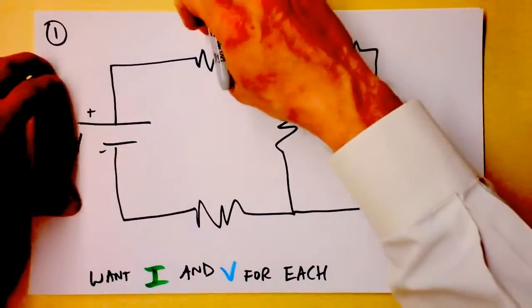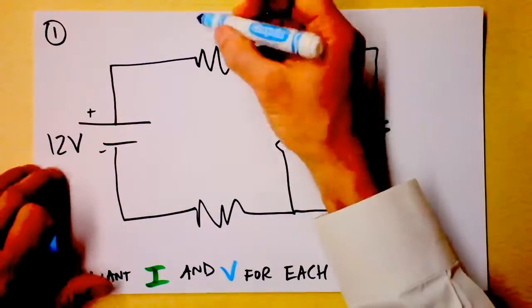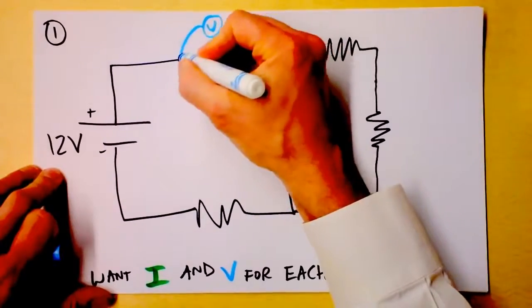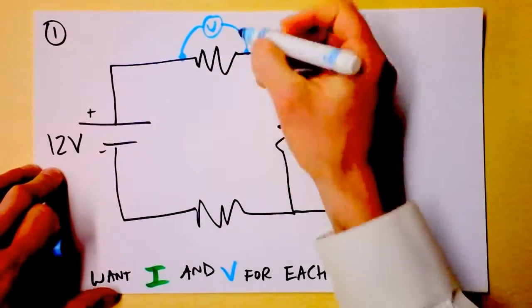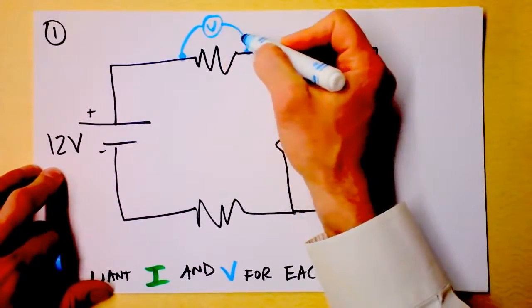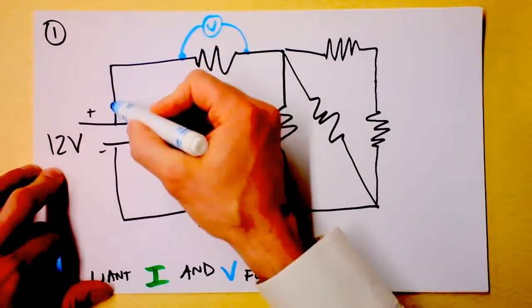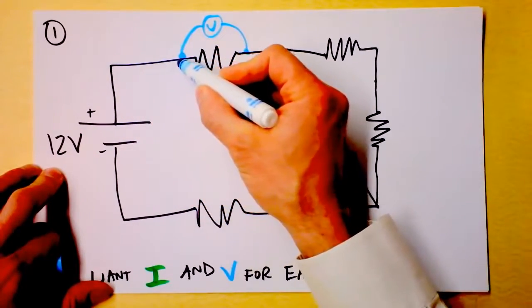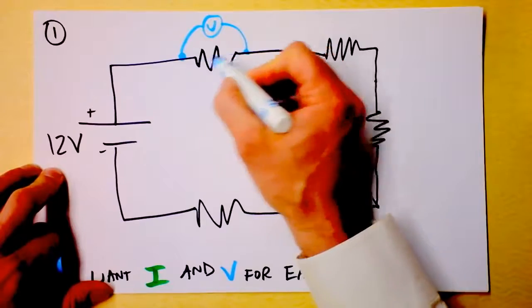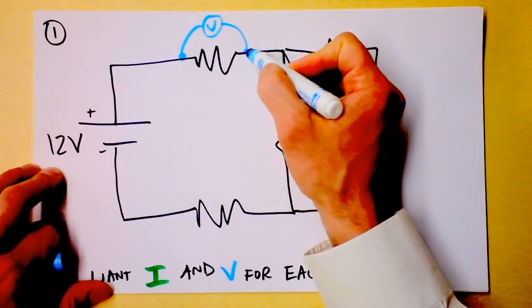Voltmeters would come on here like this. I'll just draw you a voltmeter. Here's the voltmeter that comes on here, and you would connect like that. Because see, an ideal voltmeter has infinite resistance and no current. Given the choice, the current's coming out here, the current's like, oh, I see infinite resistance or some finite resistance. Chooses to go through the resistor.